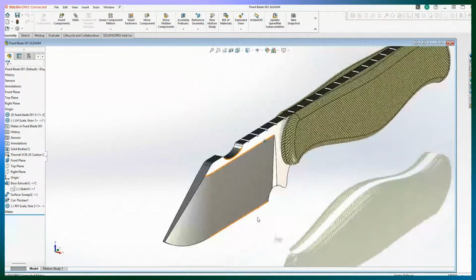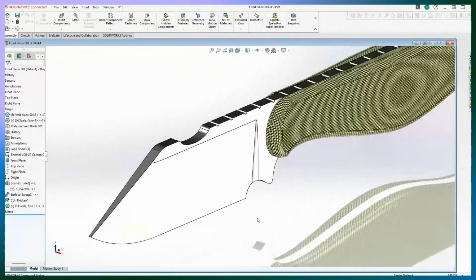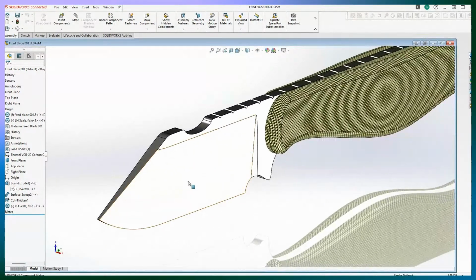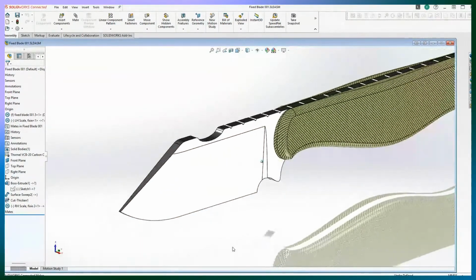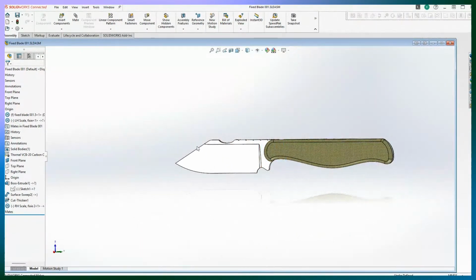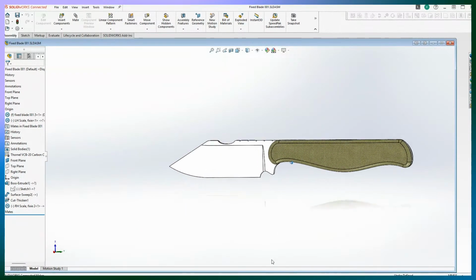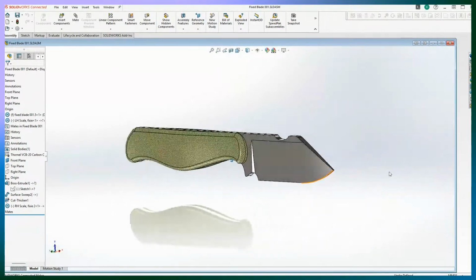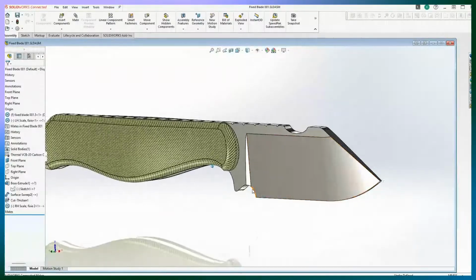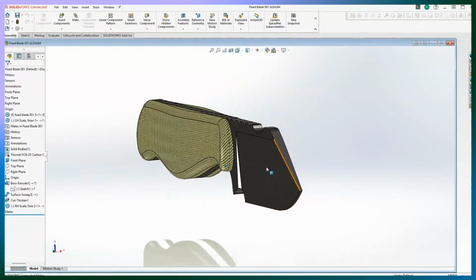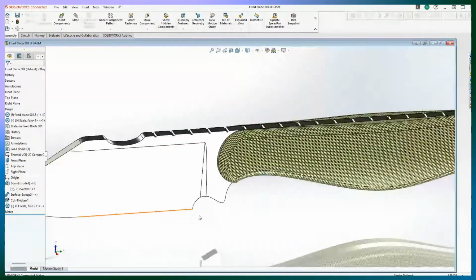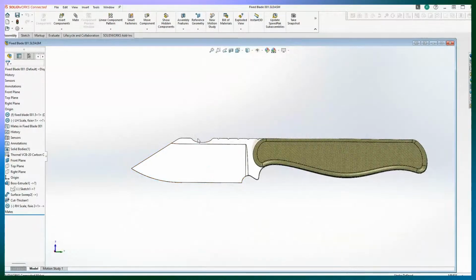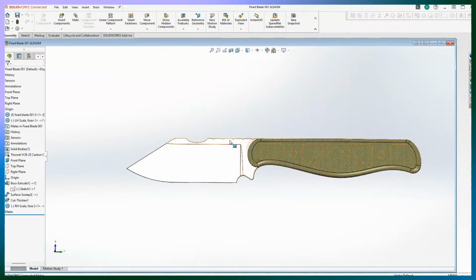Before I would attempt to have this made, I would talk to someone. Well, I probably wouldn't have the bevels machined in anyway, so I'd just do a side water jet cutout of this and then have someone grind in the bevels, the primary bevel until heat treat and then the secondary bevel. But all these other features will already be water jetted or laser cut into the material.